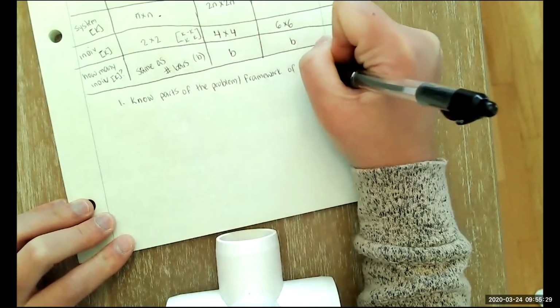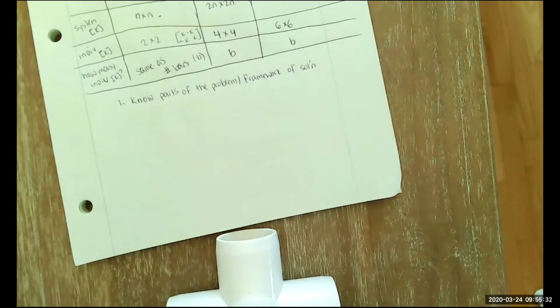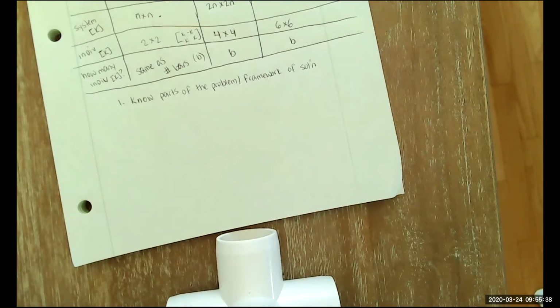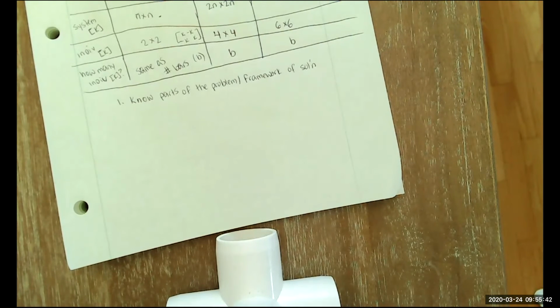of the solution. So first we define our nodes and bars, then we set up our individual stiffness matrices, then we form our system stiffness matrix, then we can apply boundary conditions. For this problem, for beams and frames, we also have to consider fixed end forces and moments before we write our system equation. And then we can start partitioning and solving. So just have a look at the examples and the homework about how we step through each portion of the problem.